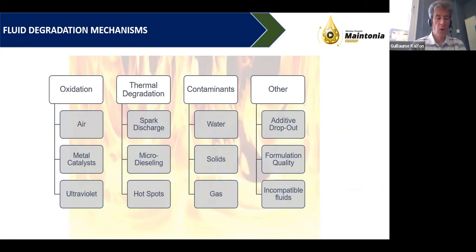So this causes the creation of very small grains of soot inside the oil. Or also, and this we can spot with thermographic analysis of the whole equipment, we can have hotspots in machines that will be too hot for the oil to handle, and this will also cause the kind of degradation that promotes varnish formation.